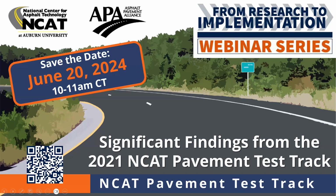Now, if you're doing an OGFC or an ultra thin bonded, obviously you're going to have way higher rates with that stuff. And we get it that in the real world, when the humidity's high at night and you've got to cover up what you milled and so forth, it's hard to do higher rates. But I think everything that we've seen is that good tack quality is super important to pavement performance. Absolutely.